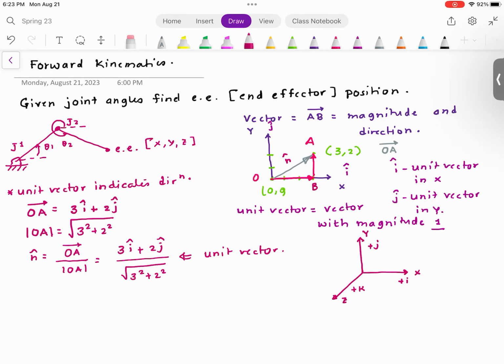When you studied statics and dynamics, probably you looked at counterclockwise and clockwise rotations. But please understand, now we are working in 3 dimensions. Something clockwise from here is counterclockwise from there. So do not rely on those sign conventions. Curl your fingers. Look at the direction of the thumb. If the thumb is pointing in the same direction as positive x, positive y, or positive z, then that rotation is positive.